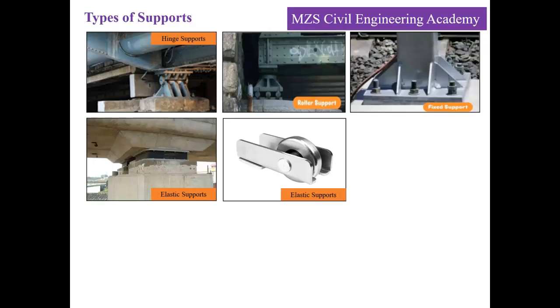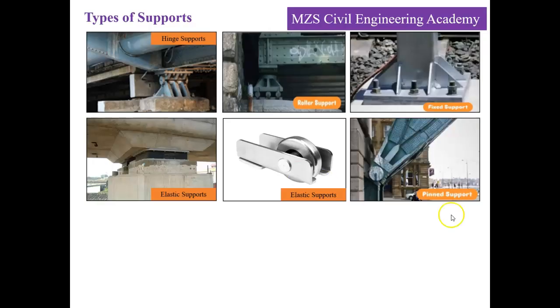For example, the pin provided at the ends of the support allows slight rotation along your truss here. Another example is the connection between the truck and its trolley, which is executed with a vertical pin inserted in the eye hole of the connection here, which allows translation, and we can find that the trolley is going to have rotational action.